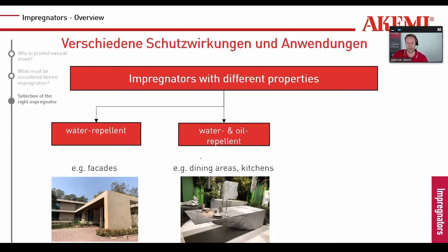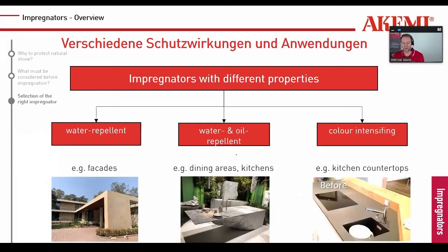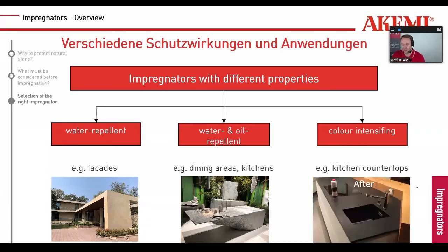Or all of them could also be color intensifying or neutral. What you just saw on the stones which I've treated before, you could not see if there was a sealer on top or not, because this was not color intensifying. But sometimes, especially when it comes to dark material, you may want this color enhancement. And this you can see on the right side down here, this kitchen countertop before the application of a color intensifier and after the application. You can see you get the rich dark color out of this granite.